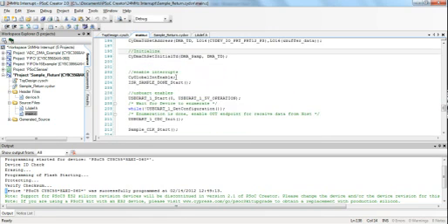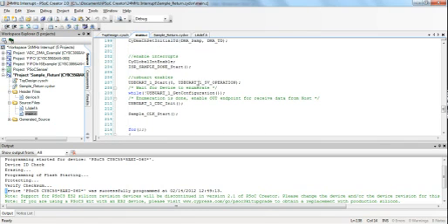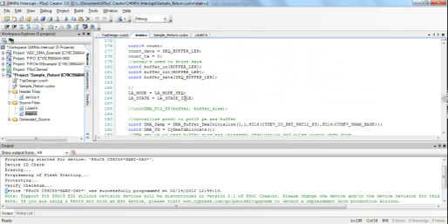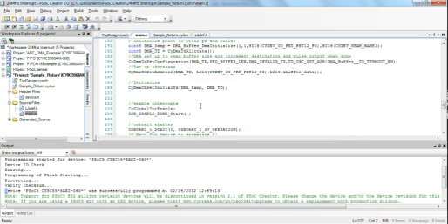The interrupts are turned on, the ISR is turned on. The USB is started in 5 volt operation. Wait for it to enumerate, then initialize it, and then start the clock. Once the clock is started and the DMA is enabled, it will do that. Right now, the logic analyzer starts in sequential mode, which is the only mode I have right now, and idle.